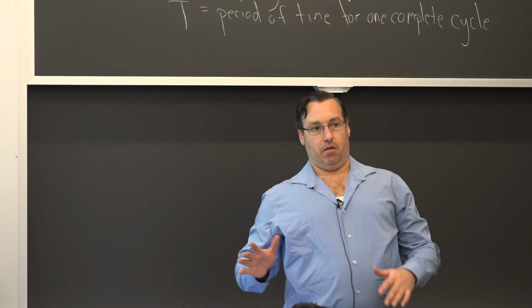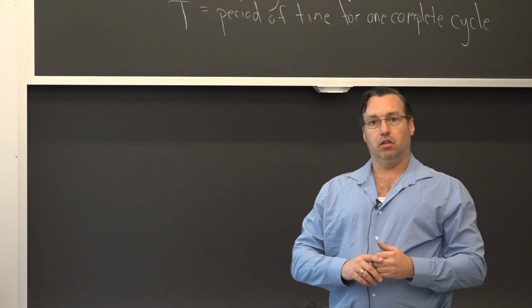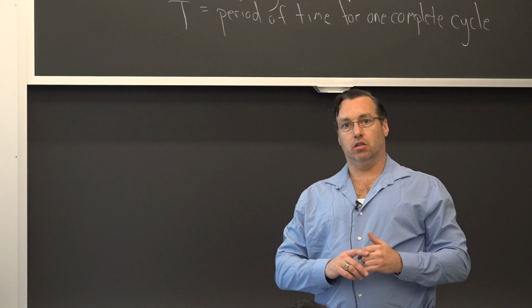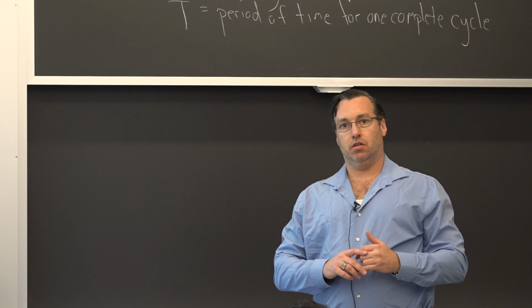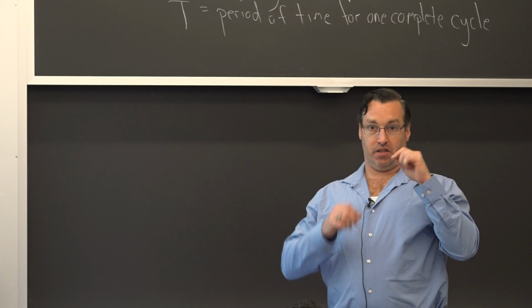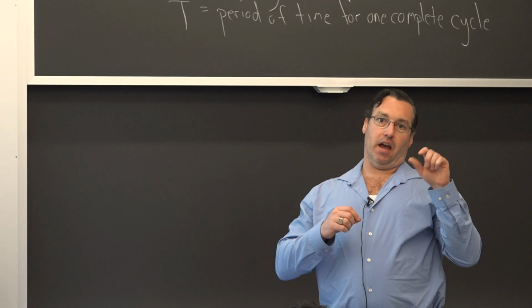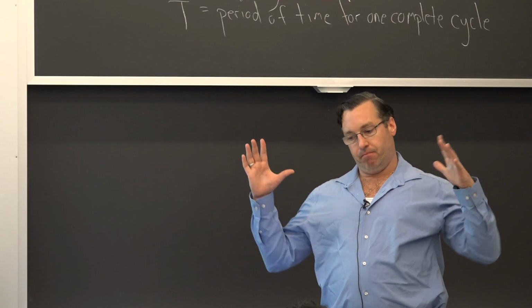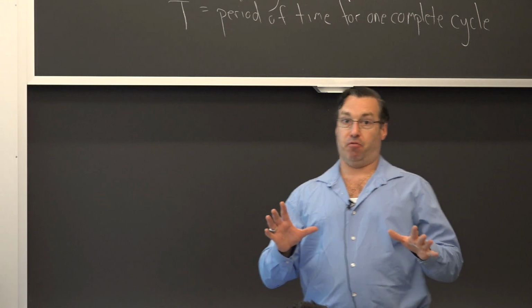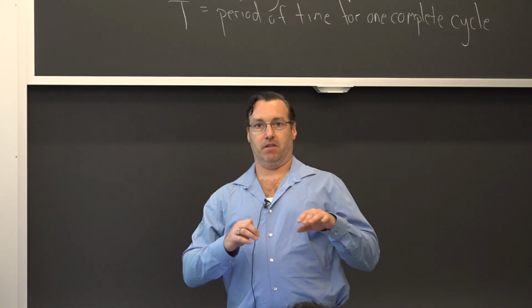So based on what we discussed, the CT sample is for mode 1 fracture mechanics. Is there any tests for mode 2 or mode 3 that you know of? Generally what they do with the CT sample, they'll make mathematical corrections for mode 2. Mode 3 is separate, so there's different types of samples.